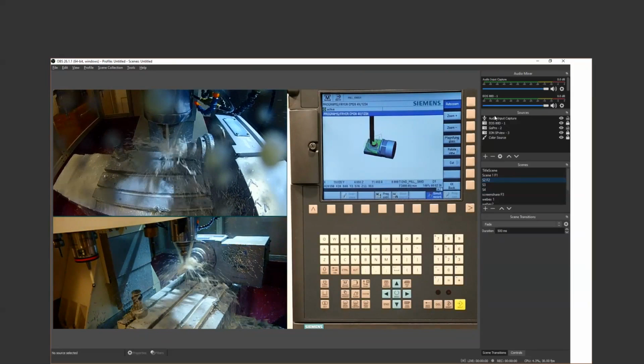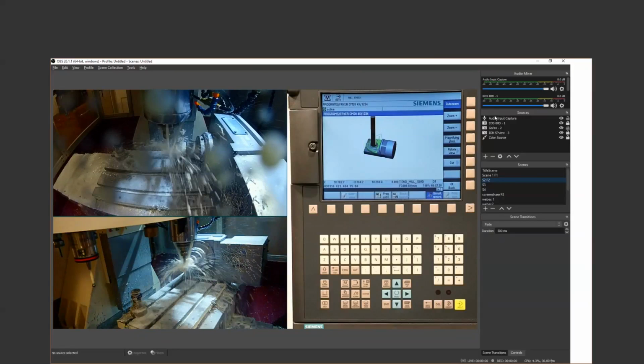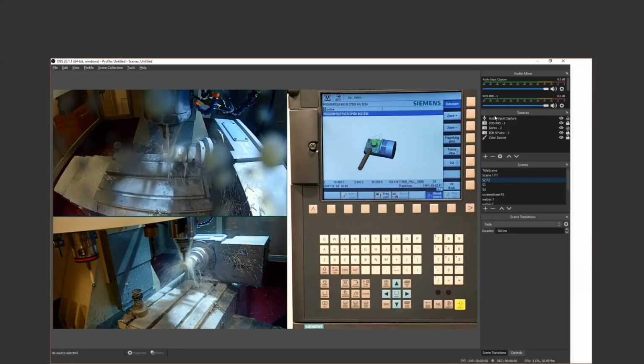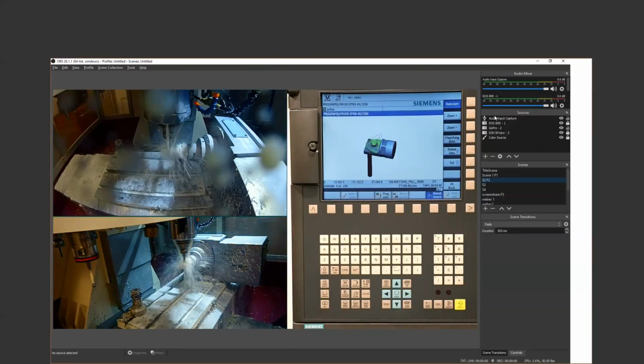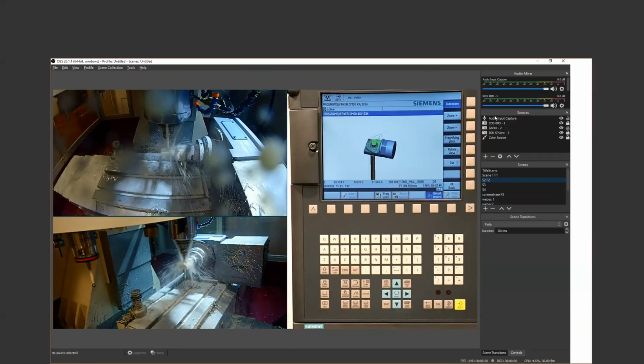So here we're doing that pillar cut. Right? There, we were cruising on that. Now we're going to do a little more traditional planar milling. So we did drop the RPM a touch, I see.